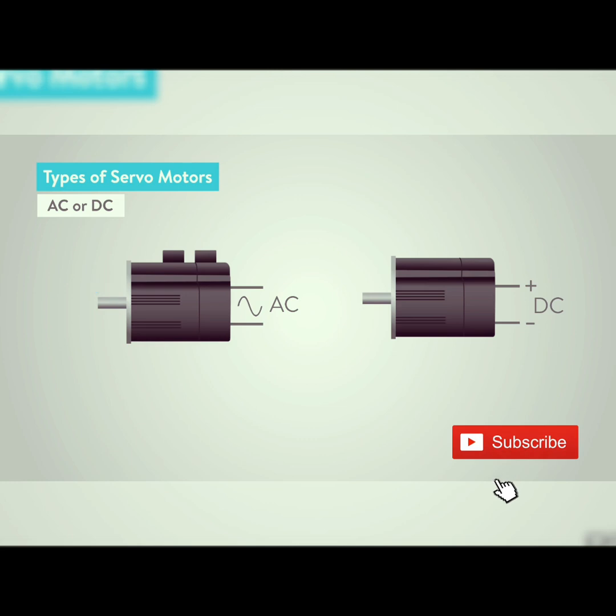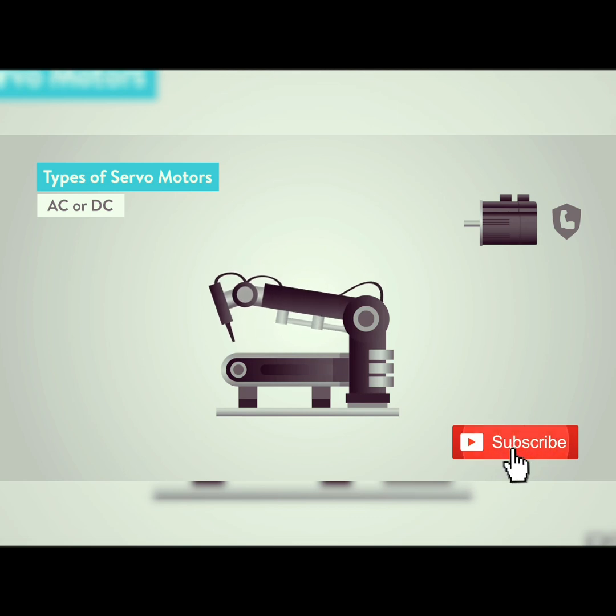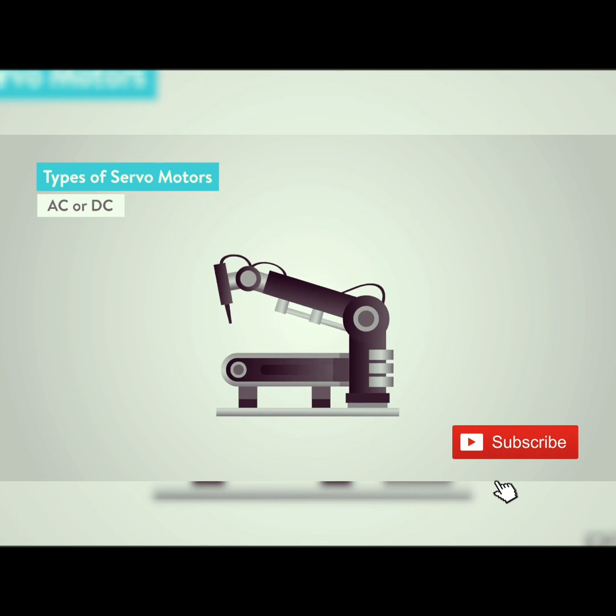magnetic poles. While both AC and DC motors are used in servo systems, AC motors will withstand higher current and are more commonly used in servo applications such as with robots, inline manufacturing, and other industrial applications where high repetitions and high precision are required.